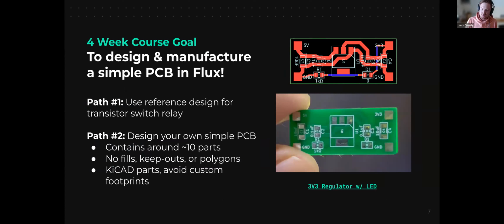Just pushing the switch will trigger the base current of this transistor, and that will close the collector and emitter, switching on the coil. And we also have a flywheel diode here to avoid any reverse voltage stored on that coil once it's turned off. So we're going to add all of the parts here, starting from the top right, the screw terminal block, up to the battery here.